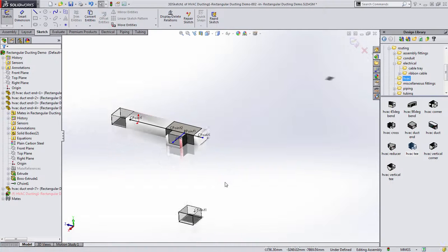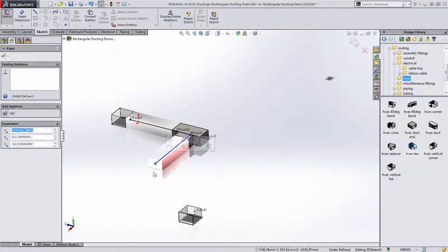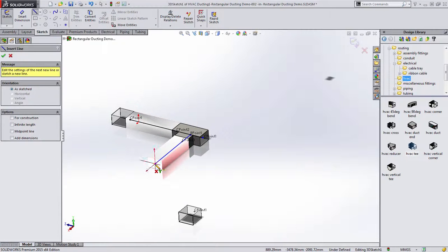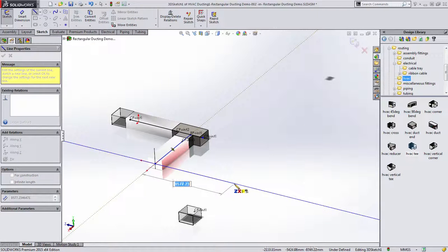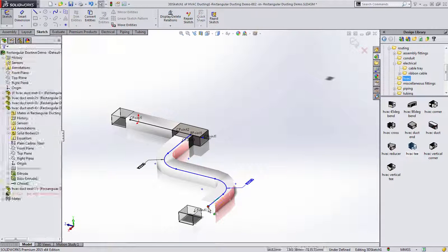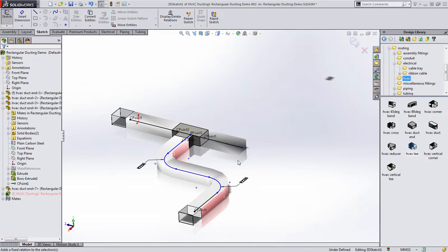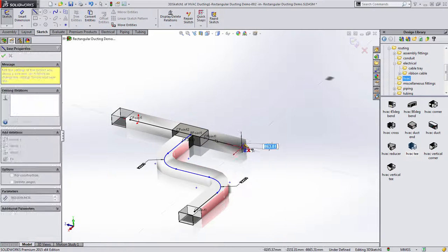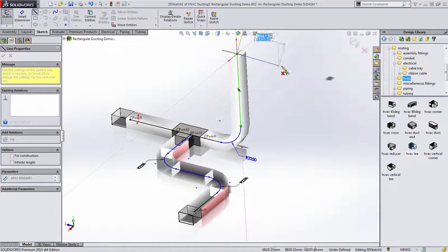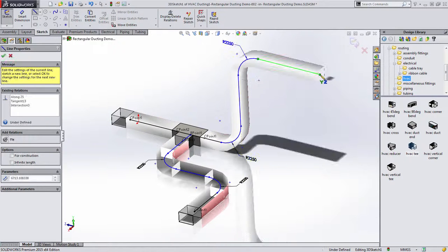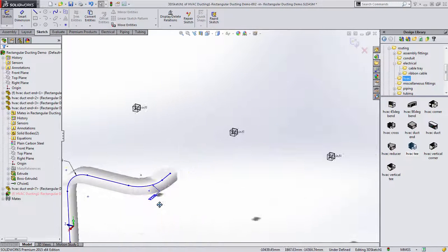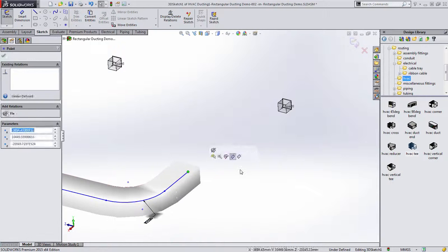You're able to add constraints to the route sketches, as well as align them to existing geometry, which greatly simplifies getting the duct positions correct. The ducting is not limited to 2 dimensions either. You're able to add ducting with vertical connectors as well. This really allows you to do detailed HVAC infrastructure for facilities and get the complete layout specified.